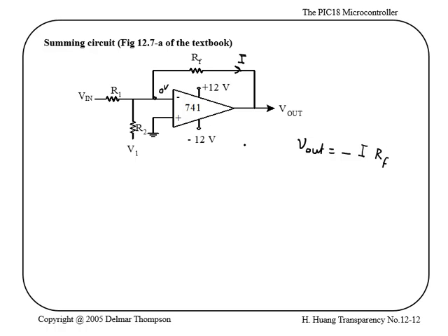And if you look at I, it is going to be I1 plus I2, which is Vn over R1 plus V1 over R2. So V1 is the voltage that you are going to provide, and that, for example, could be 3 volts, 3.3 volts, minus 5 volts, whatever. Right? So you have flexibility in picking R1, R2, RF, and V1.